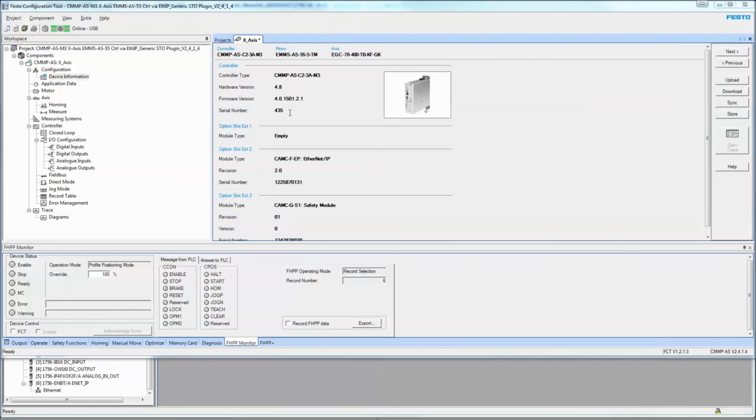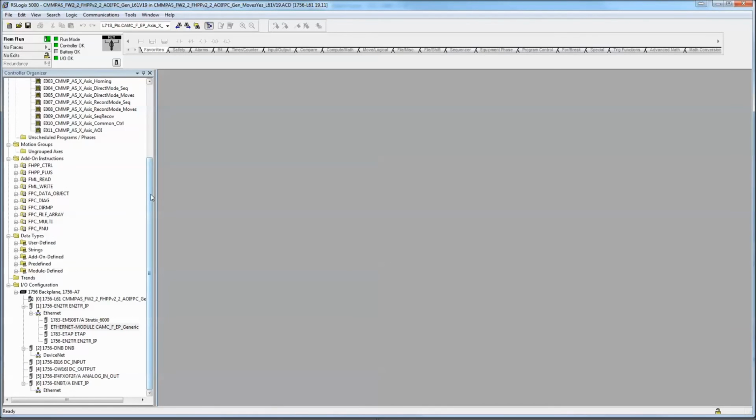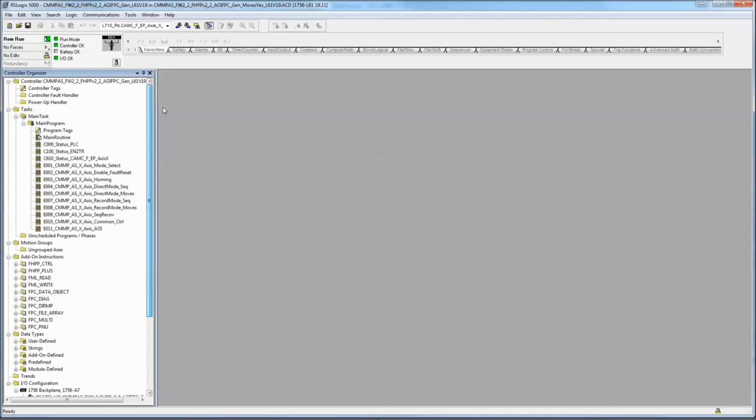The difference is that in version 2.1 and older, there is a run idle diagnostic header, which amounts to 4 bytes or 1 double integer in the input data structure. So now that I have downloaded and upgraded, this is the same project in this series, but the firmware is different. This code here is still the same, which was working on version 2.2.